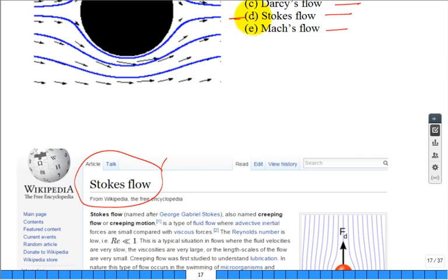Now, if I have a cylinder or a sphere, and I have very slow flow over it, you think, well, that never happens. But it does happen, and there are some cases in practice. If you're interested in the settling out of small, fine particles in stationary or stagnant air, you can find the aerodynamic effective diameter of that particle and consider it's dropping like a sphere, in Stokes flow. It may take a long time for it to settle out.